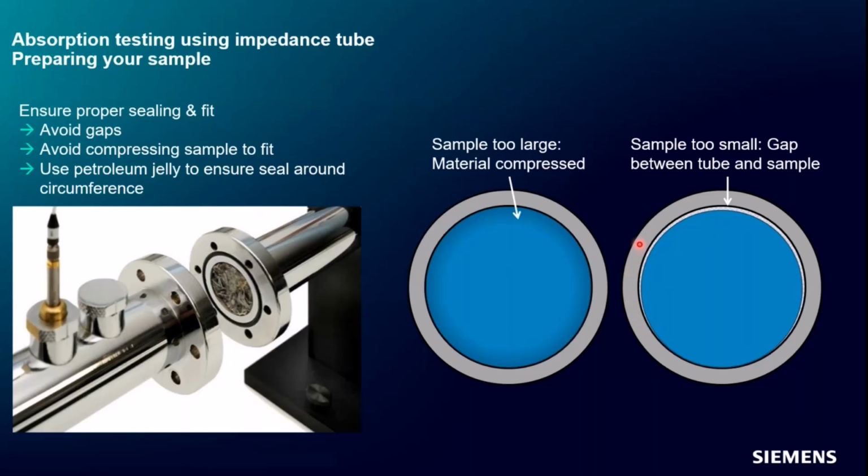So as far as the sound wave is concerned, it's going to look at this and it could bounce off of that, but some of my energy will be absorbed, or it can bounce off this rigid wall in the back, and it's going to do both of those things, and you'll be fooling yourself thinking you're measuring just the effect of the material if you have that gap.